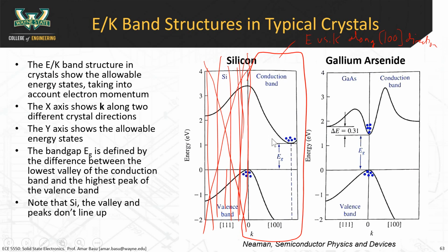All right, so let's look at what this band structure is. At zero momentum, the electron has zero energy. That's the top of the valence band. Remember, the valence band describes electrons that are covalently bound to the lattice. An electron covalently bound to the lattice is not moving. That would be an electron here on the map. An electron that's moving with a fast velocity would be out here. The larger the wave number, the more momentum the electron has.